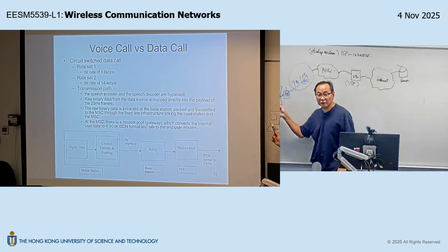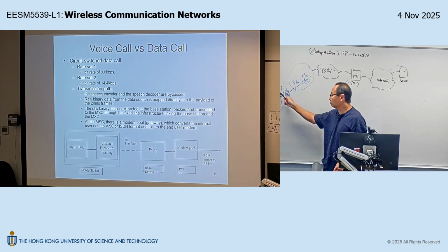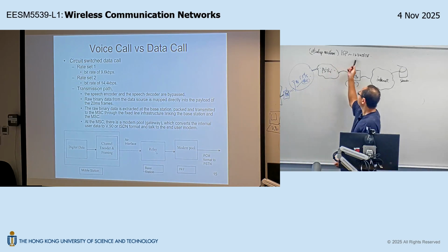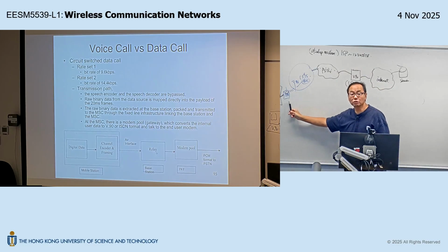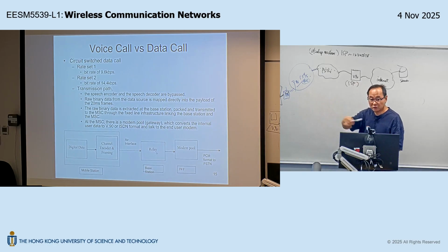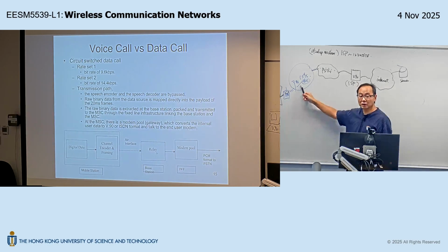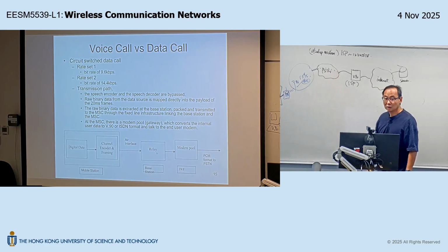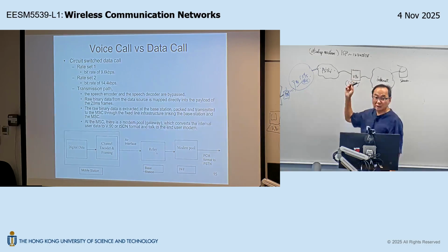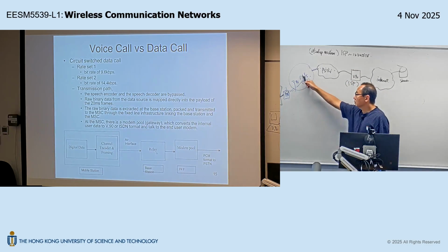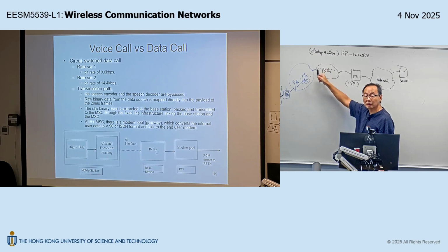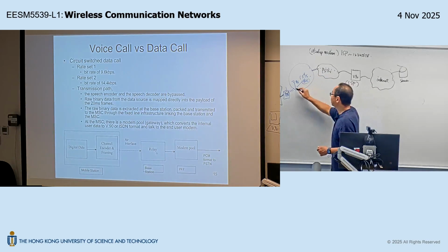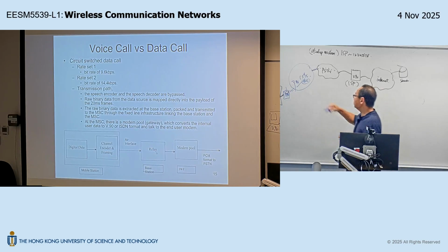So when you want to access internet outside, what you need to do is you have to, through the COM1, ask this mobile to dial the number 1, 2, 3, 4, 5, 6, 7, 8, right? So you need this mobile to make an outgoing call request. So this mobile will send an origination request through the access attempt we just explained to the base station. Base station will move on to set up the entire call path, right? So since 1, 2, 3, 4, 5, 6, 7, 8 is a fixed line number, so the IS95 base station and base station controller and the mobile switching center eventually will set up the path to the PSTN because it's a fixed line number.